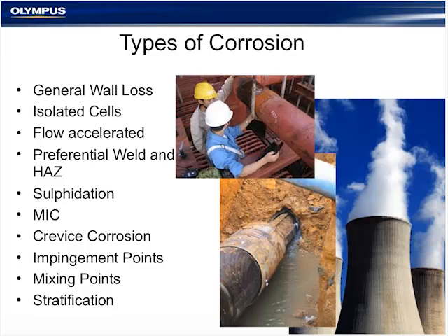However, you can also find instances of corrosion where you'll find isolated cells. And this is more common where you see, for instance, where water might separate from a process fluid, and that water might pool in a particular spot, and that would result in concentrated or uneven corrosion in a specific area. Similarly, flow-accelerated type corrosion, where the product itself is abrasive. It essentially acts as a sandpaper and is sanding the pipe from the inside out, and is often found that you're gonna find these isolated type corrosion, especially where there's some sort of focal point or some sort of bend in a pipe, something like that.